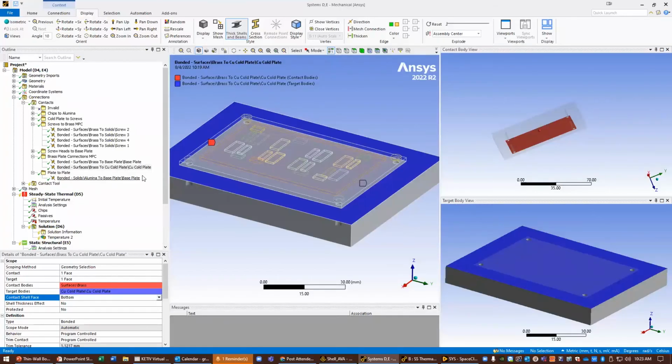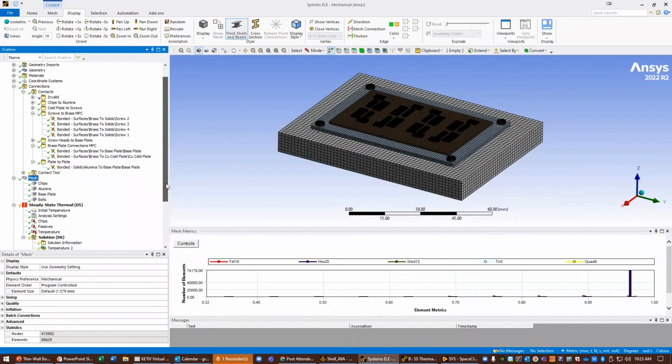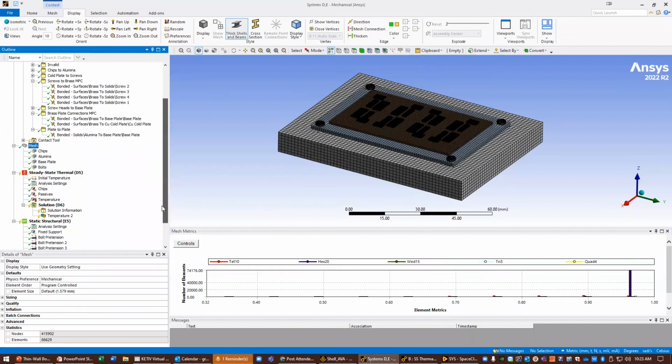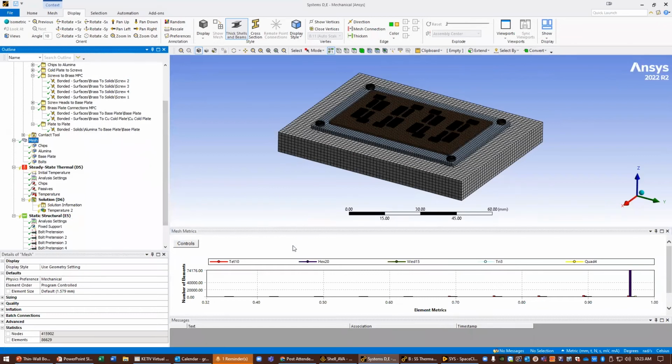So with those caveats, essentially now I've taken my mesh, which was in the 5 million range using a solids model. And now I have very good element quality here, where most of my mesh is in the 0.95 range. I don't have any elements less than 0.2.